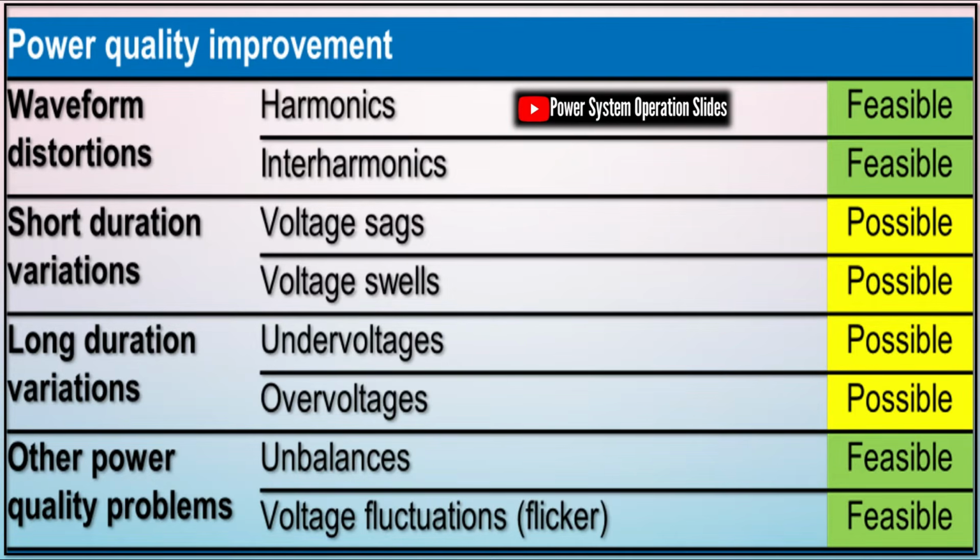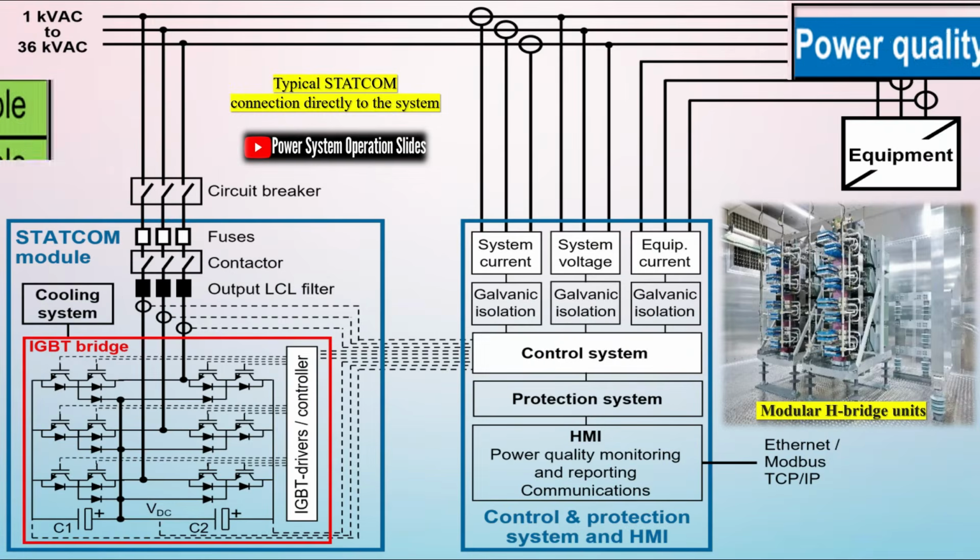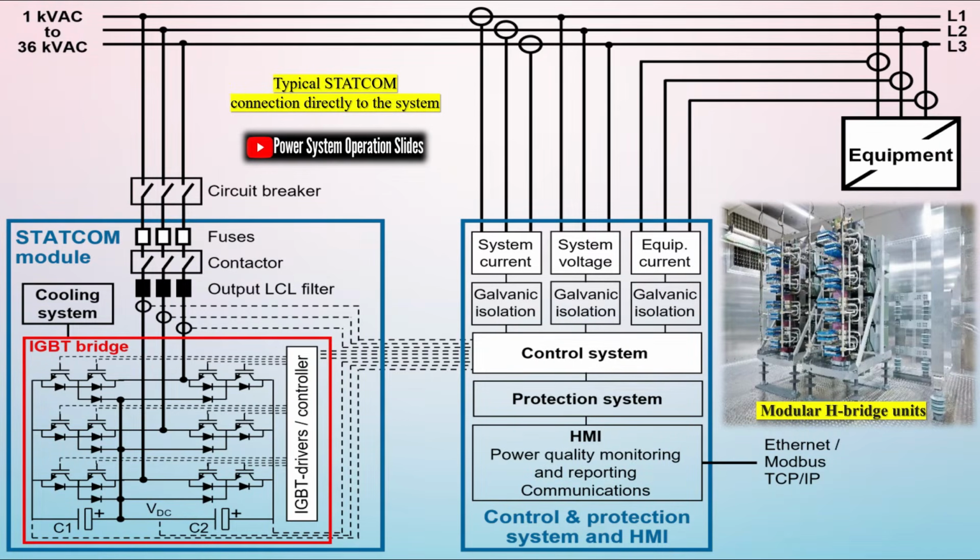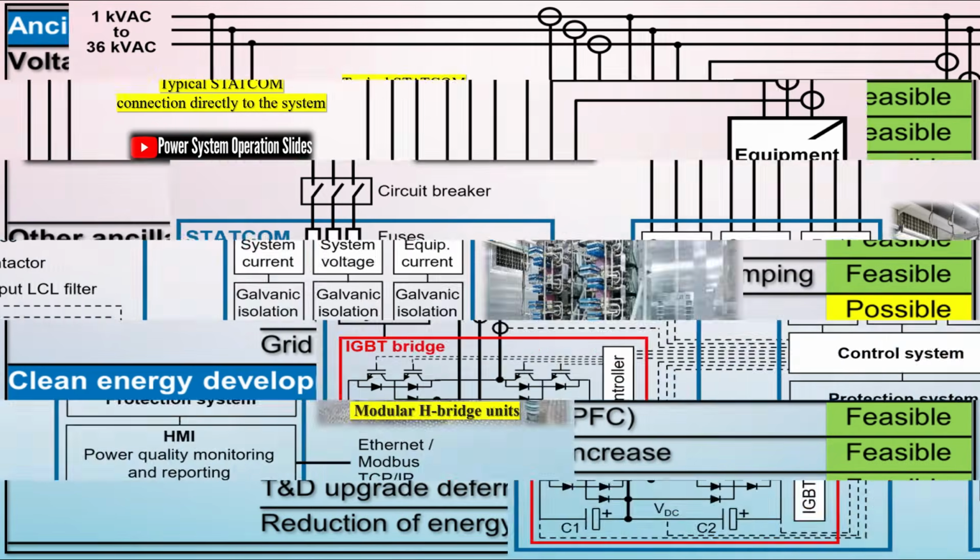Modern grid codes also demand that wind farms remain connected during short-term disturbances, such as voltage dips caused by faults, a capability known as fault ride-through (FRT). During such events, the PCC voltage can drop sharply, creating a surge in reactive power demand. Without adequate support, wind farms risk disconnection, exacerbating grid instability. STATCOM and SVC provide the necessary reactive power swiftly, helping maintain voltage and allowing the wind farm to ride through faults without tripping offline.